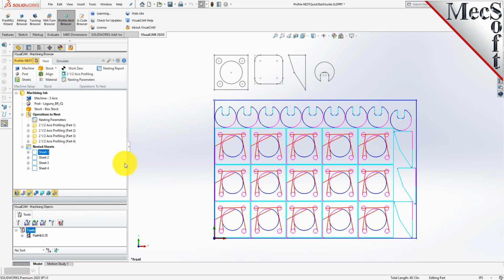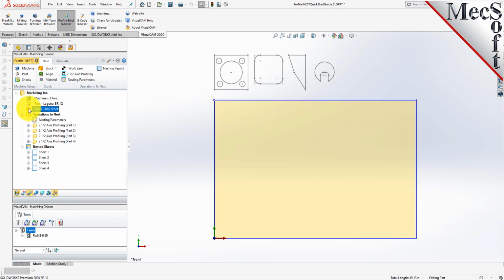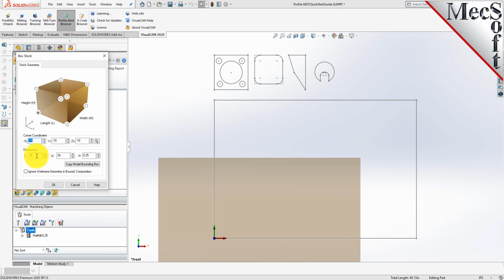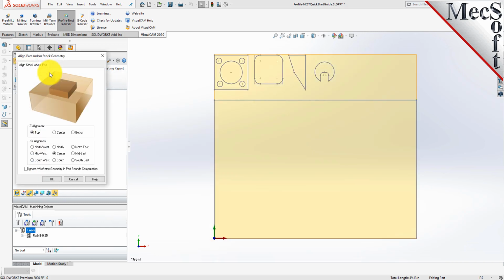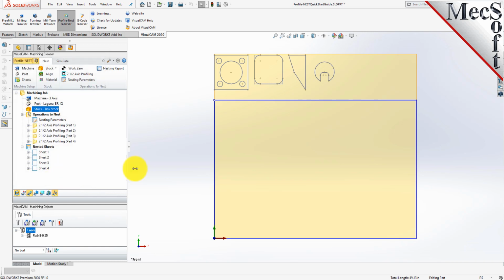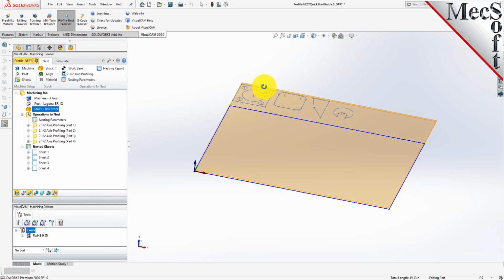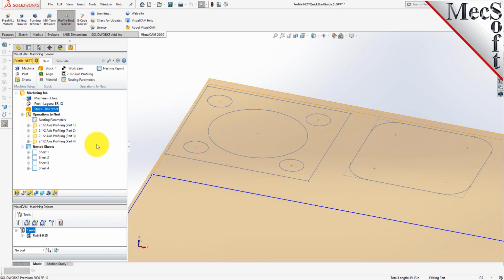And since we don't have any stock coming up there, let's go ahead and change the dimensions of our stock to go up that high, so it extends up so we can see a good view of the cut material simulation. So let's go to isometric view and let's go ahead and do a simulation. Let's slow that down just a bit and pick play.